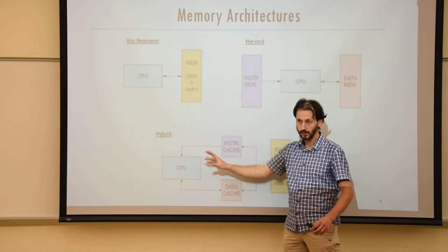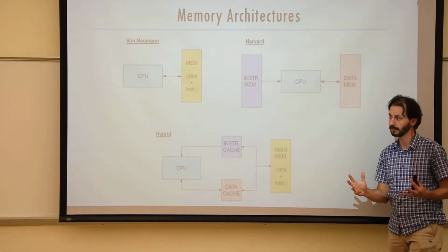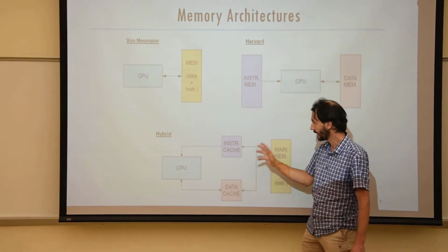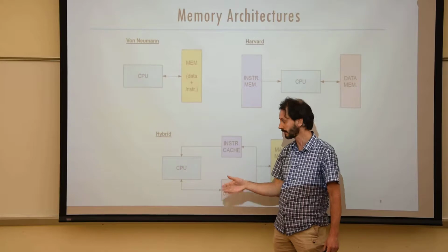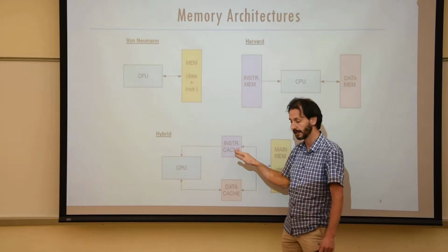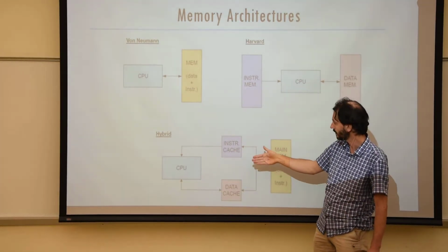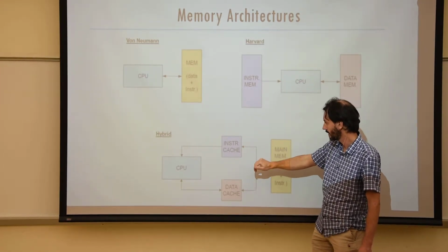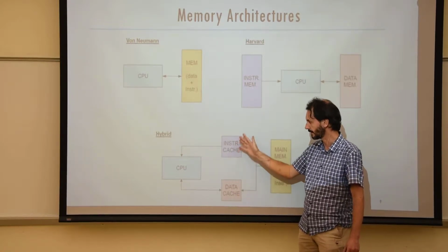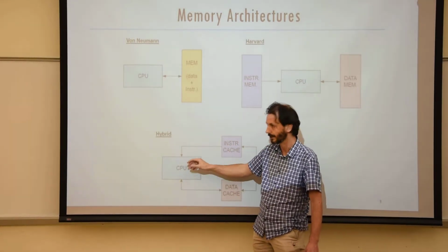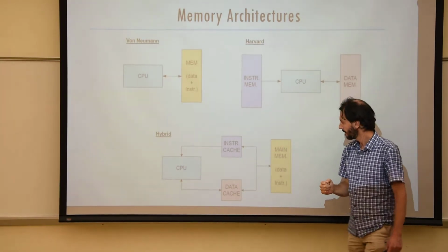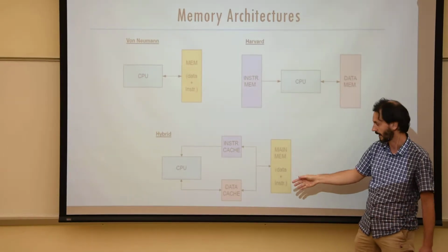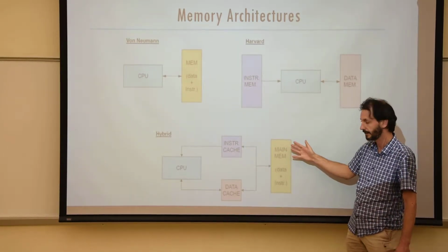The cache is very close to the CPU, it's very fast, so you hope that what you want to use is actually in your cache, so that you can immediately fetch it and compute very fast. There's maybe only 10 cycles. You have different caches actually. You have what we call an L1 and L2 and also an L3 cache, certainly in a multi-core processor. Let's say your L2 cache costs 10 cycles. If it's in your L1 cache, even closer, you have say 1 cycle latency. But if it's not in your cache, you need to go out of the CPU and it costs you about 100 cycles to get it from main memory, like DRAM.